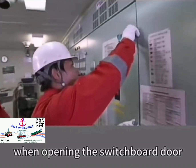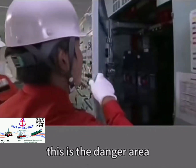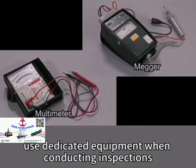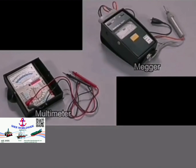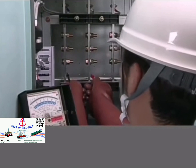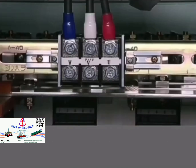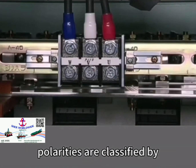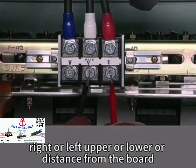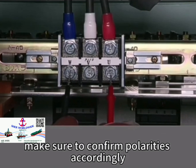When opening the switchboard door, stay away from the electrically charged section. This is the danger area. Use dedicated equipment when conducting inspections. Due to the nature of switchboard design, polarities are classified by color according to their positions: right or left, upper or lower, or distance from the board. Make sure to confirm polarities accordingly.